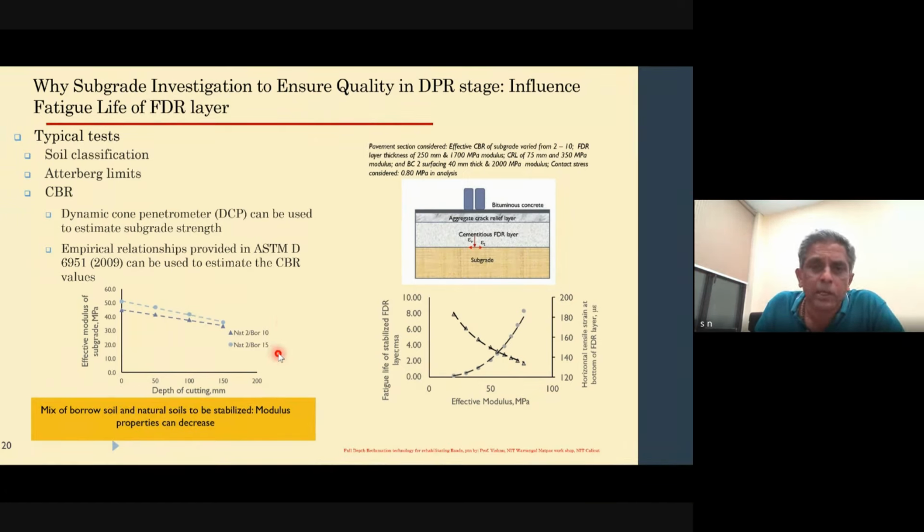Now, along with that, before stabilization is done, you need to make sure that you do a visual inspection of all the locations so that any subgrade issues, water-related, drainage-related issues can be identified a priori. Utility structure, utility facilities identification can also be done as a part of the initial preparation.